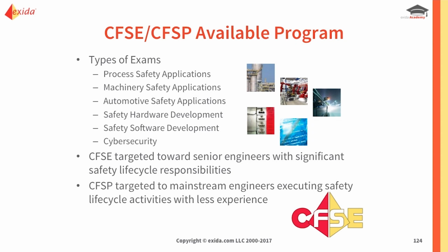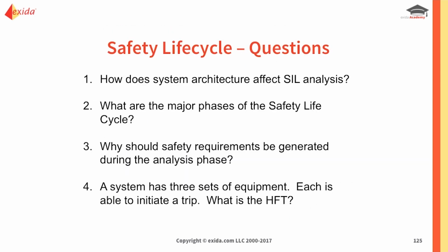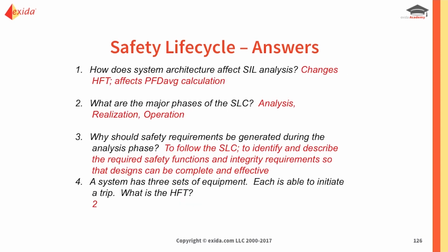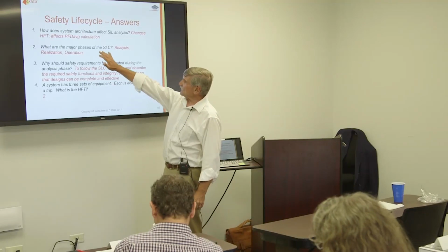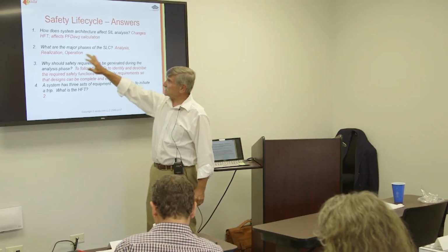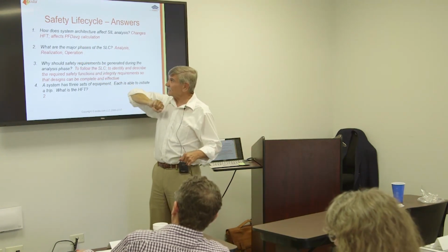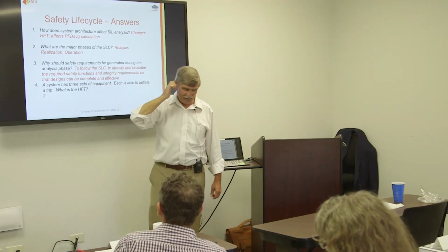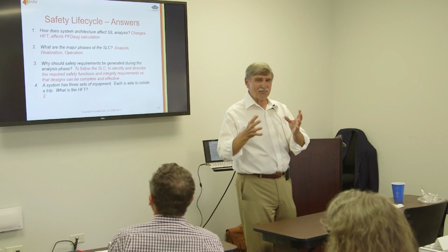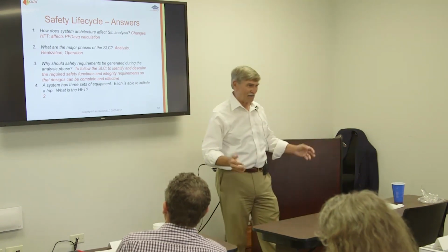Anyway, let me just run through this briefly because this is fun stuff. I just wanted to ask, does system architecture affect SIL analysis? And what we meant by this term is redundancy. And yes, it changes the hardware fault tolerance, but even far more importantly, it has a major impact on the PFD calculation when you take into account the redundancy, which is exactly what you'd expect. The three major phases: analysis, realization, and operation. Why should safety requirements be generated during the analysis phase? Because those who do the risk analysis must communicate their needs to those who do the design.